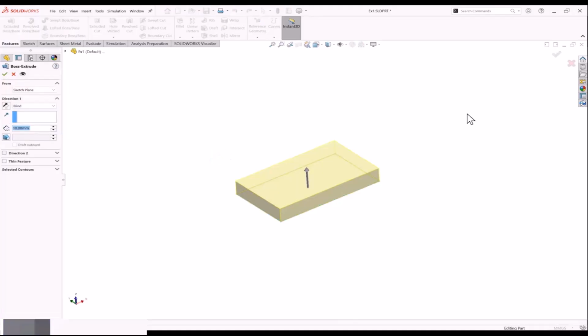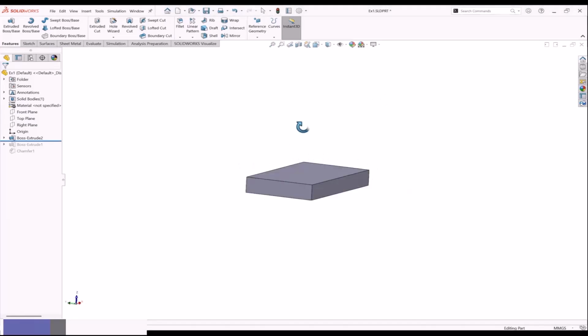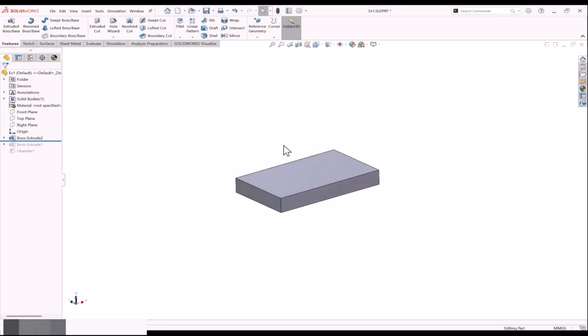Okay. So when you're making a sketch, you can take help of this origin to define your objects and then extrude it. Now this body will have a different origin because the 3D object has a different origin. You cannot see the 2D origin anywhere now. So how can we see the origin of this body? For that, there is the hide and show option. Click on the small arrow, go to the option origin, view origin. You can see the origin here.